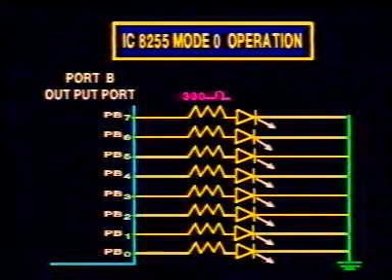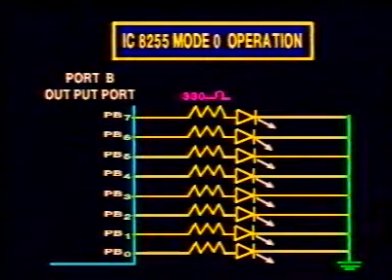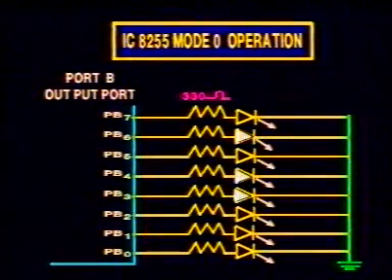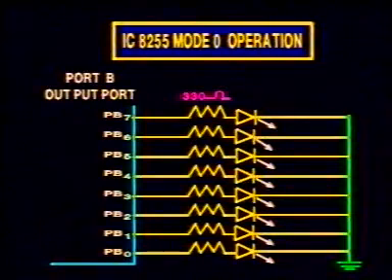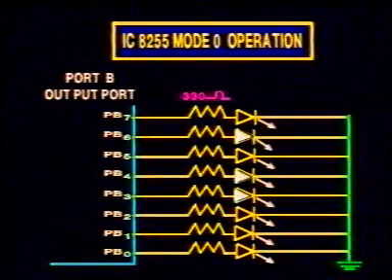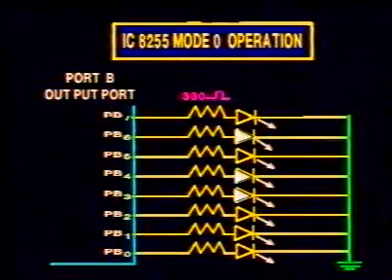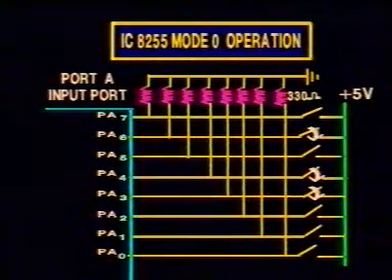The accumulator content becomes 0101 1000. The out instruction puts this data into port B. When these instructions are executed, the LEDs connected to PB3, PB4 and PB6 become on. The LEDs which glow now correspond to the switches that are closed.